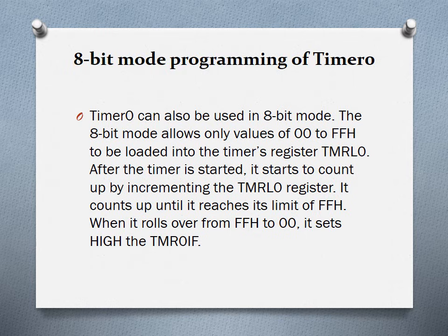Another register which is associated with timer 0 is the INTCON register. The INTCON register will have an interrupt flag bit which is present inside it. So all these registers are needed. Proper understanding of these registers is needed for the programming of timer 0.